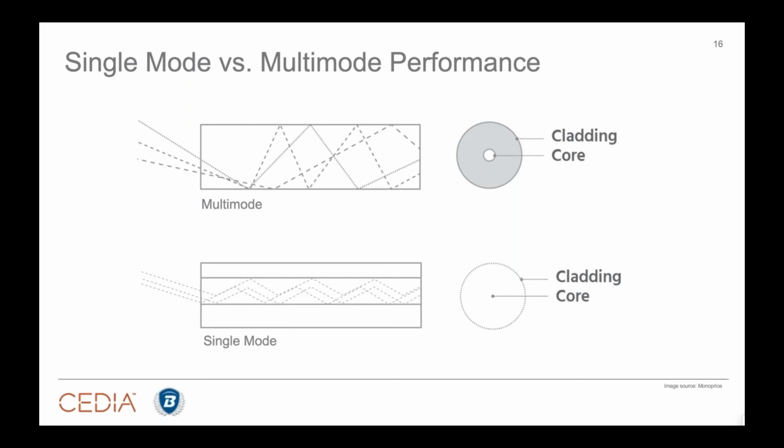A thicker pipe, a bigger pipe like multi-mode, the aqua-colored cable with a 50-micron core, can send more simultaneous waves, but they start to get sloppy. And that occurs at about 1,000 feet. This is why you see single mode being integrated in a lot of applications. In fact, single mode usually costs less than multi-mode. It's a very universal cable for a lot of different environments. Now, multi-mode has a purpose. You can send more simultaneous waves through it. You can handle different frequencies very, very well. But really, I tell folks, think of two things. If you're doing a retrofit, stick with whatever cable has been installed. If you're exceeding 1,000 feet, never pull multi-mode. Don't do it. Go to single mode.